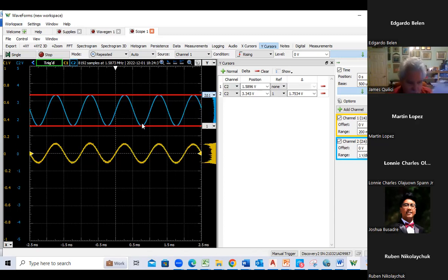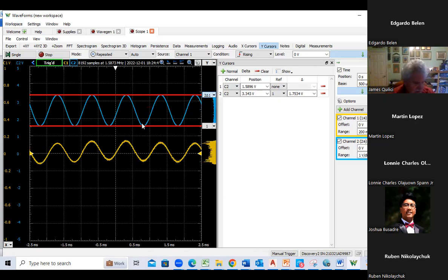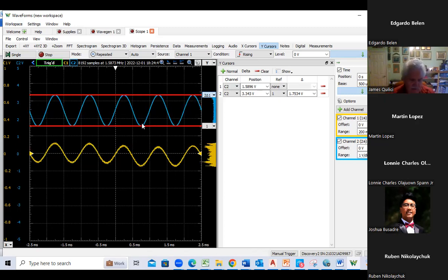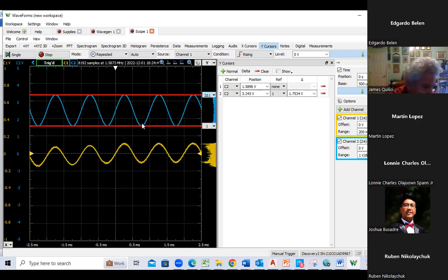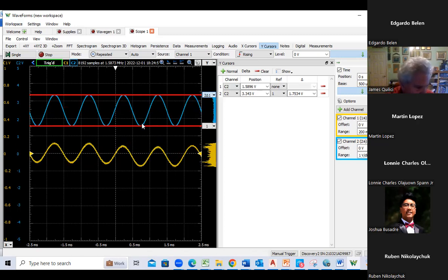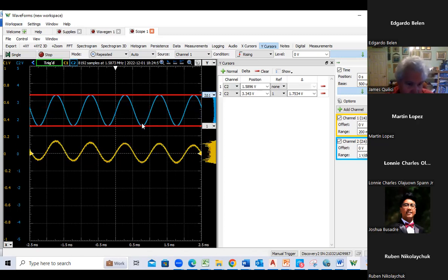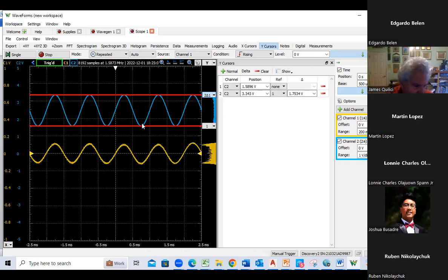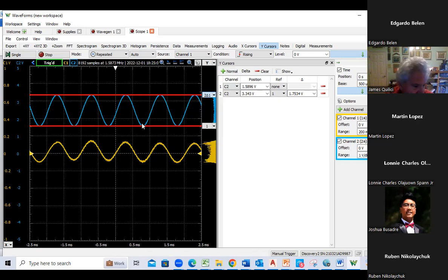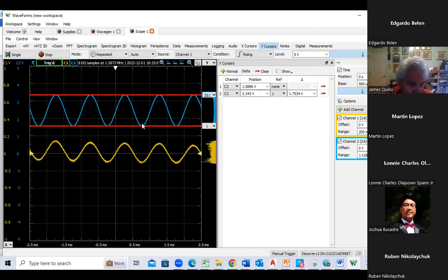So anyway, as far as doing this lab and making your measurements, I sat here, I had to dink around with it and tune it up. Part of the reason, again, is I didn't write down the values that I simulated last week. Hopefully you can start with your simulated values. And again, you might have to use resistors in parallel or series. Just try to get them as close as you can. What's always key, though, is getting the base voltage where you had designed it to be.